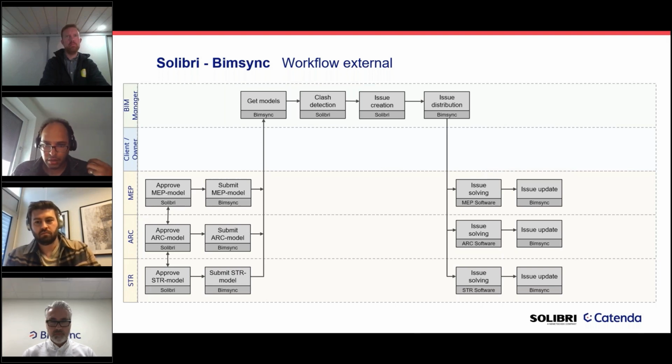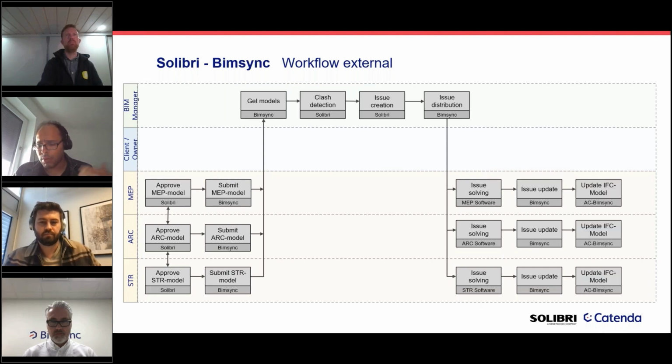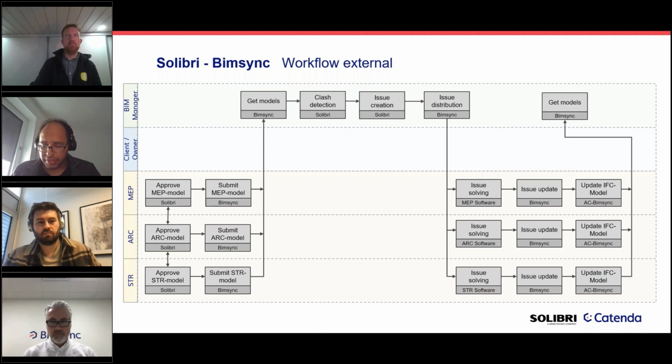David would then see on Bimsync or even in Solibri directly that I have done something to this issue, in this case, change the status to resolved. I will also update the IFC model from Archicad directly to Bimsync or any other authoring software. David will get these models again and confirm this issue or close these issues.